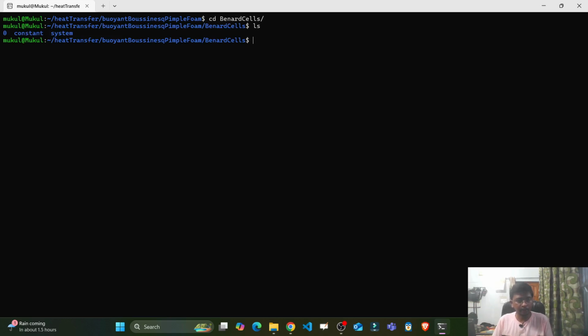Here you can find the 0, constant, and system directories. There is no Allrun file. If there is no Allrun file, what will you do? Don't worry, you want to check what steps we have to perform. For example, first we have to go for blockMesh or not. If the mesh is already given, then do we have to go for snappyHexMesh or not, or is it required or not. Then we have to check for decomposePar or some other commands.